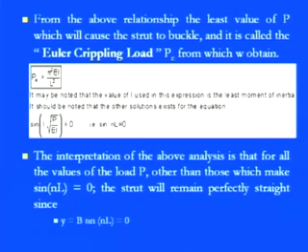So that's why, since this is a limiting case for the strut, it is known as the Euler crippling load. From this we can say that PE, the Euler crippling load, is equal to pi squared EI divided by L squared. It may be noted that the value of I in this expression is the least moment of inertia, and it should be taken carefully, because this is the area moment of inertia, so we have to be very careful about what exactly the shape of that particular column is.